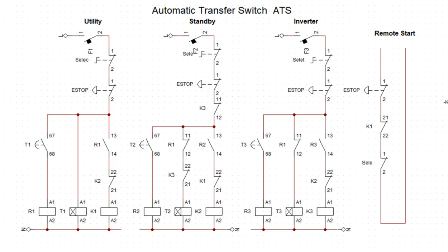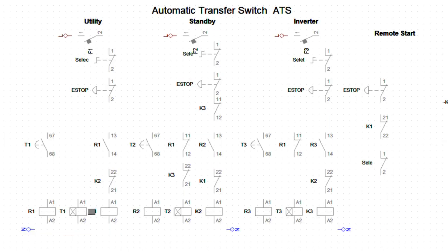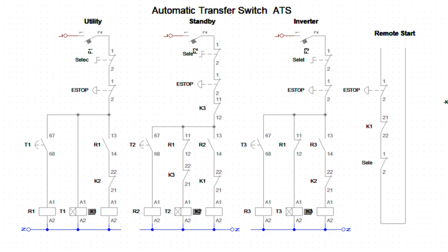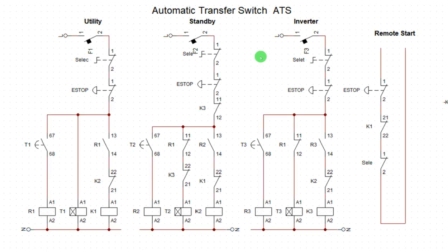So let's put on the inverter. Okay, now let's put on inverter now. It's counting. Now inverter has taken over. Look at here, it is disabled. This is K3. The contactor of K3 from inverter will close. The auxiliary here will open. So genset cannot come in unless the inverter is not active. That is only when genset will come in.